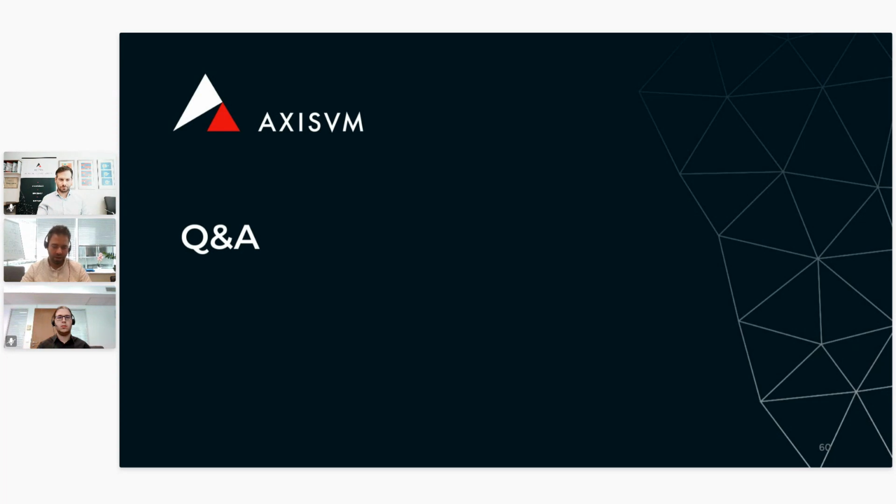If a construction stage consists of adding elements and removing elements, it has to know which happens first. And if it detects that there are construction stages which are mixed, then it will offer you a dialog where you can decide which operation happens first. Addition of elements happens first, then it is followed by the removal of certain elements, and you have to define this.